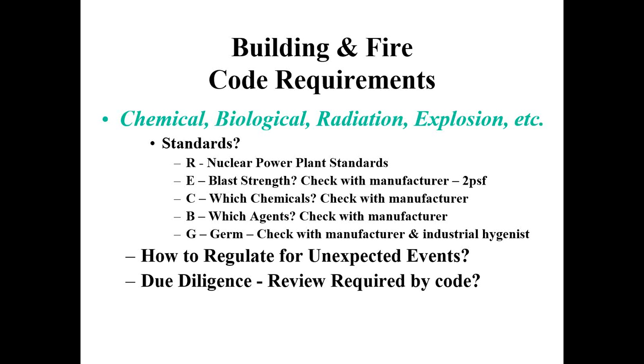At the University of Illinois Molecular Biology Laboratory, the architect specified a silicone-based firestop sealant for the whole perimeter of the building. At the time, there were spray products and cheaper products that could be used. Many tried to switch the specification but were unsuccessful because the architect had worked with the industrial hygienist from the building owner's staff, and they determined that to stop germs they would need a product that would stop moisture flow through it, and the silicone did that.